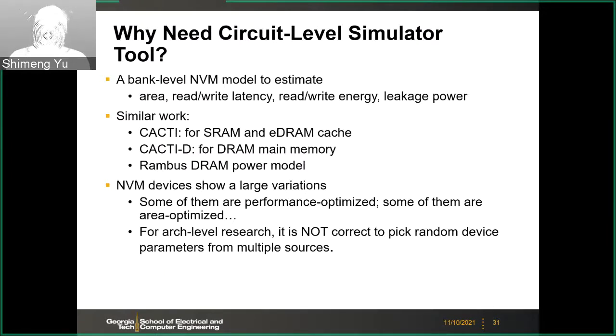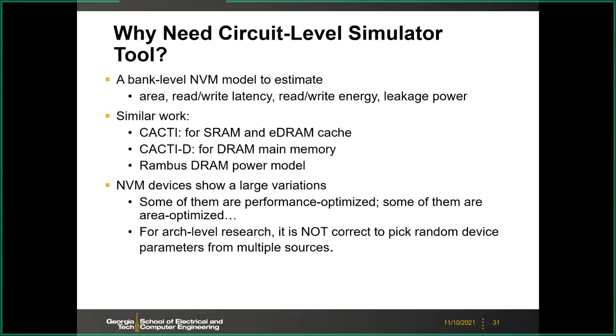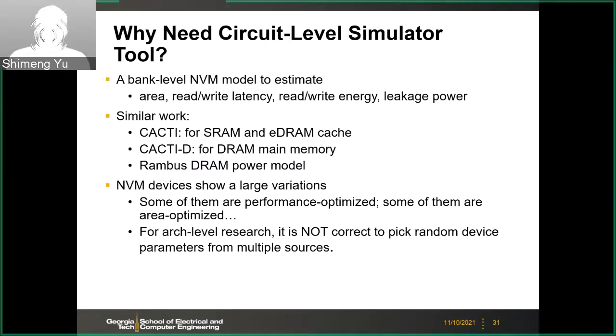We want to know the area, the read-write latency, read-write energy, and leakage power, given different design options. Because for the memory design, you can have different options, like the subarray size, number of blocks, and how many cells you read or write simultaneously. So there are many choices.